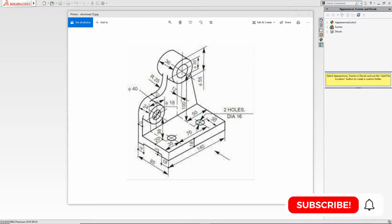Today we are going to make this simple part here in SolidWorks. This is a 140mm long and 85mm wide plate, and the side plate has different curvatures here. This is 100mm from center, and 50mm here, 20mm here, and 38mm the center of this here. This is 35 and 70, and this is 30.